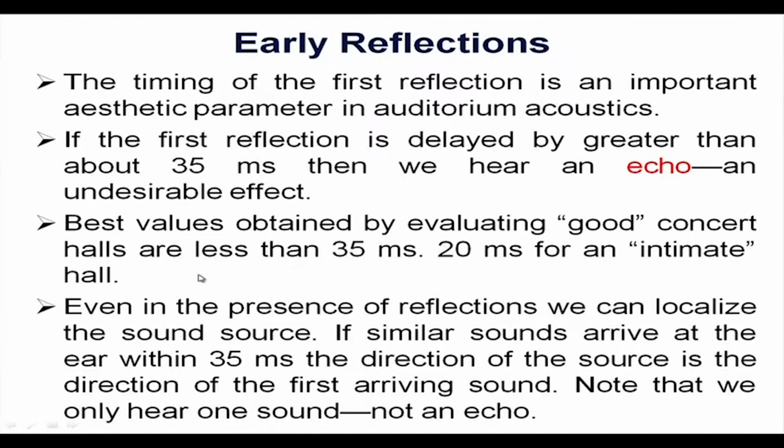hall. Okay, I will come to what intimate means and all those things. So, 20 milliseconds is good, but not above 35 milliseconds. In that case, echo will be heard. Even in the presence of reflection, we can localize the sound source if the similar sound arrives at the ear within 35 milliseconds, the direction of the source.